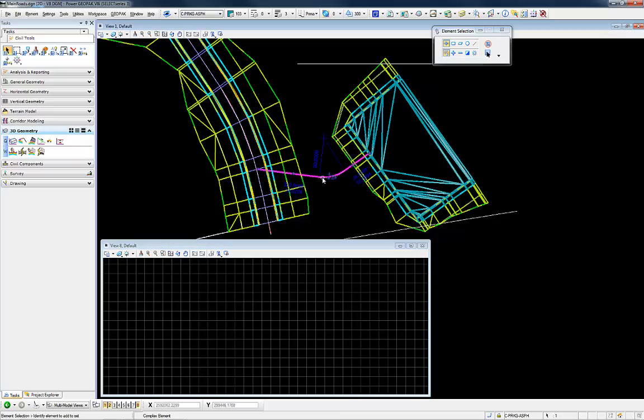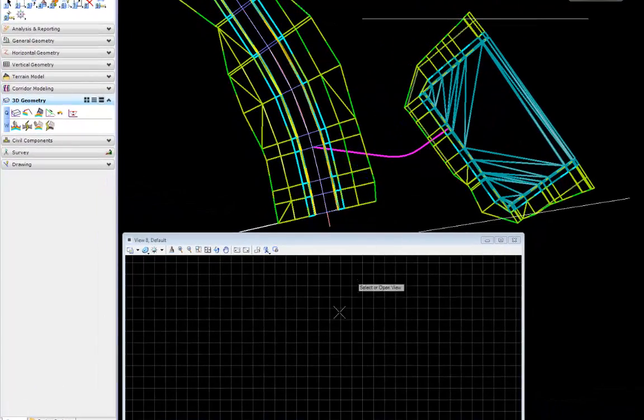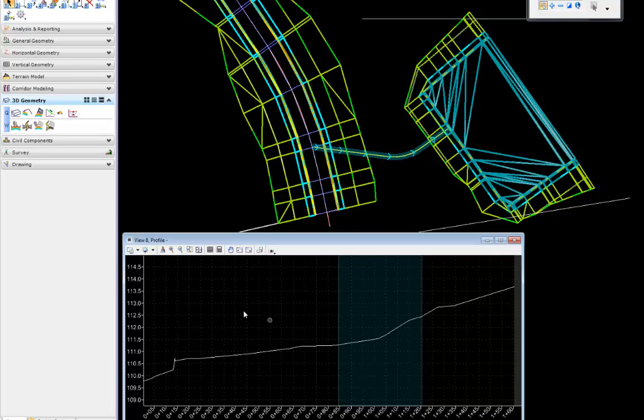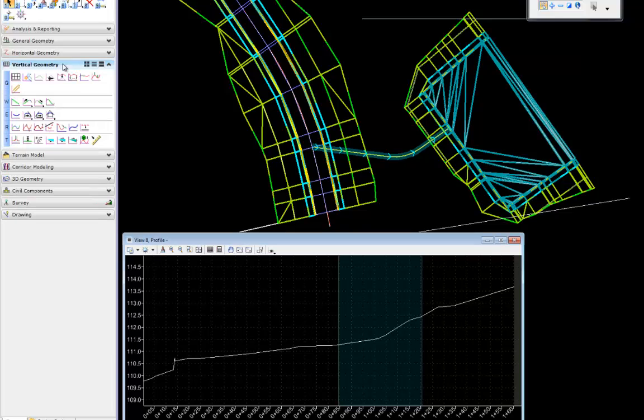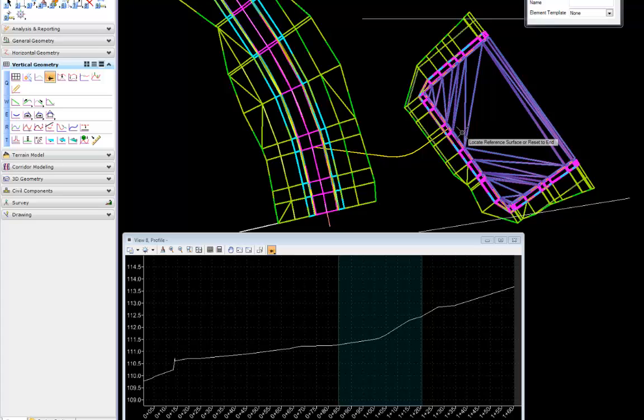With this cell, we'll place a basic road with intersections. Prerequisite for placing the cell will be an alignment between either two roads or a road and another surface type, such as a parking lot. The alignment must also contain a profile.